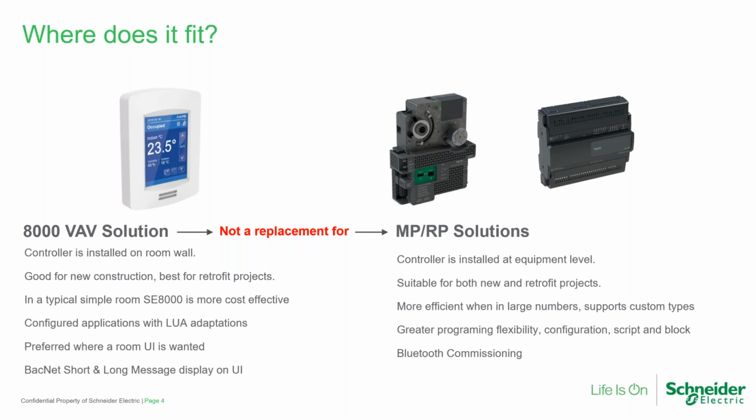They're self-contained. And these devices that you see here as the MP and RP solutions are a Schneider product, but everybody makes them in some form or fashion. They're self-contained, where you can see there's a damper actuator and a pressure transducer built onto it, and then communication, and maybe you wire some I/O into it, but it's self-contained. Typically, those applications are in your larger footprint type buildings where you're putting hundreds, if not thousands of them in, and they're typically tied back to an automation front end somewhere.